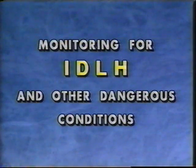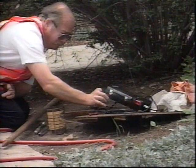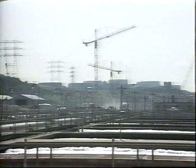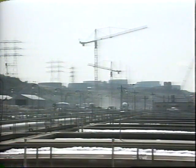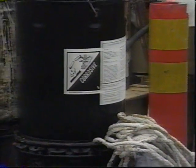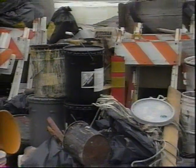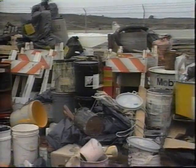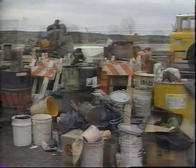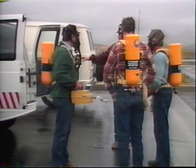Monitoring for IDLH and other dangerous conditions. As a first step, air monitoring should be conducted to identify any IDLH and other dangerous conditions, such as flammable or explosive atmospheres, oxygen-deficient environments, and highly toxic levels of airborne contaminants. Direct reading monitoring instruments will normally include combustible gas indicators, oxygen meters, colorimetric indicator tubes, and organic vapor monitors. Other monitoring instruments may be necessary based on the initial site characterization.